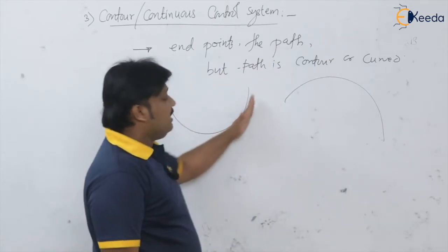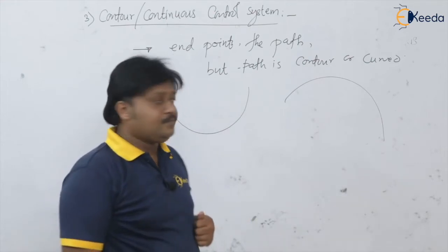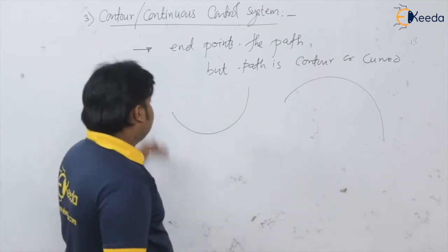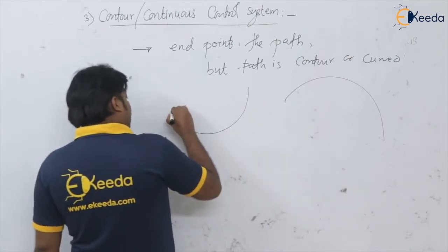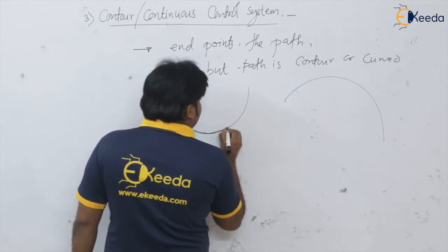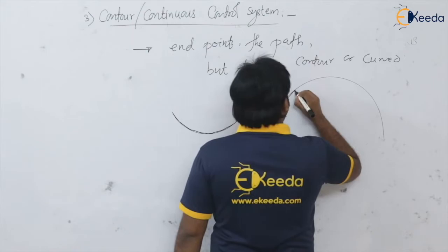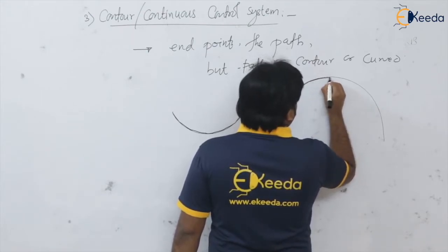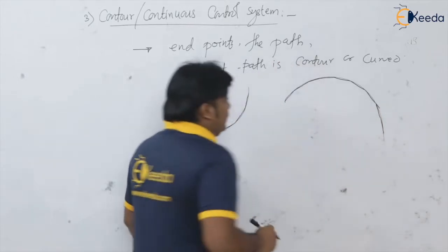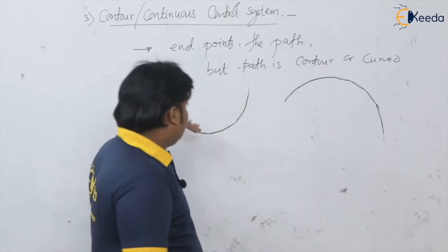Theoretically you can see the curve like this, but when you see in actual, how is the tool movement? Theoretically we can say that we can get the curve, okay, but when making this curve, the movement of the tool is again a straight line only. Please remember, the movement of the tool is in a straight line to produce this curve.